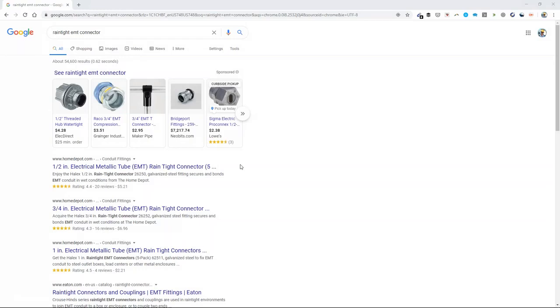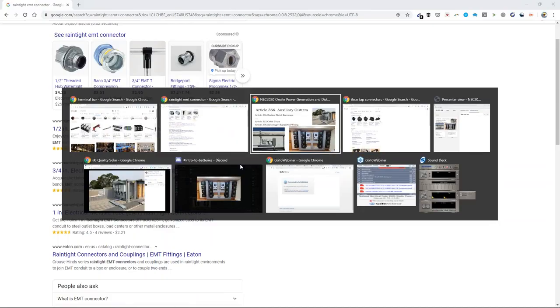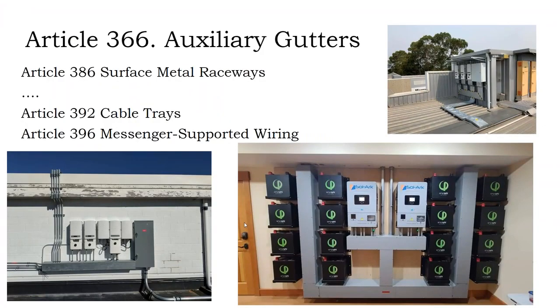And maybe if you're putting outside of conduit cable inside of that EMT, you might argue to your inspector that we're just using this conduit for physical protection, but we're not required to be in conduit, so the environmental rating of the conduit doesn't matter. I'd say inspectors would go 50-50 on that argument.